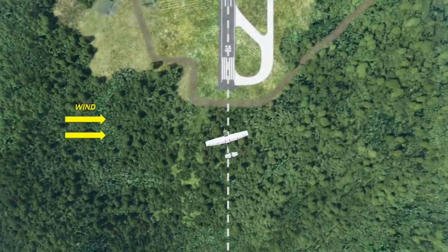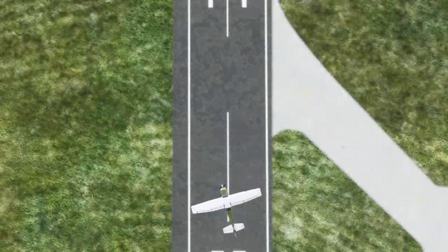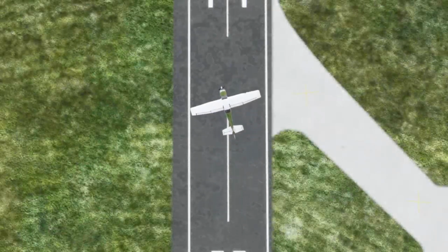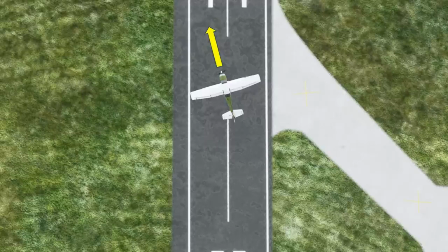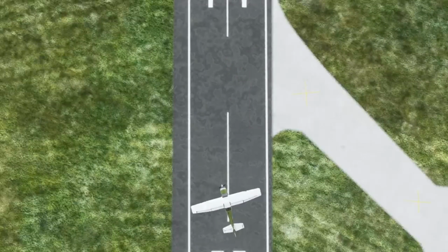This occurs when one main wheel lifts up off the ground and the airplane tips forward along the axis between the nosewheel and the main wheel still on the ground. A rollover could cause one wingtip or the prop to contact the ground. The basic factors involved are cornering angle and side load. Cornering angle is the angular difference between the heading of a tire and its path. Whenever a load-bearing tire's path and heading diverge, a side load is created. It is accompanied by tire distortion.